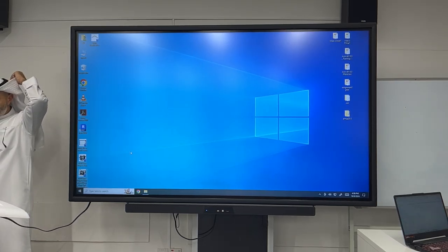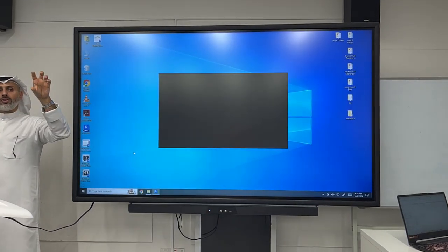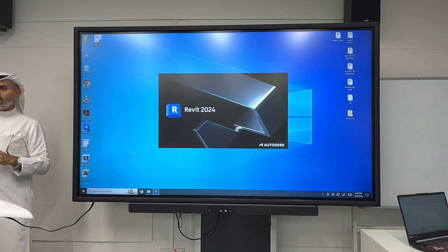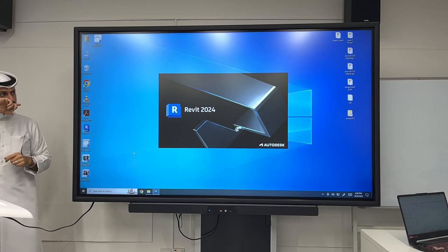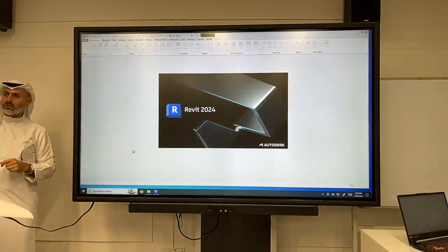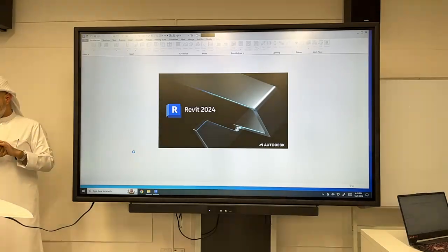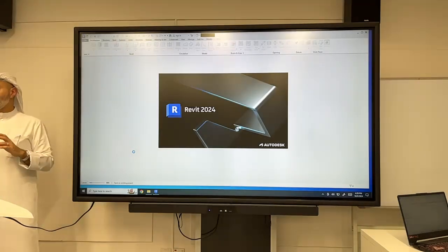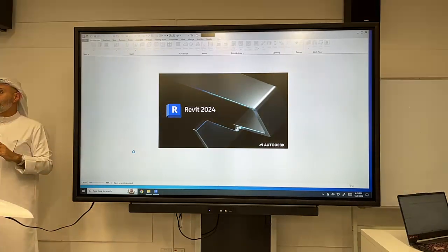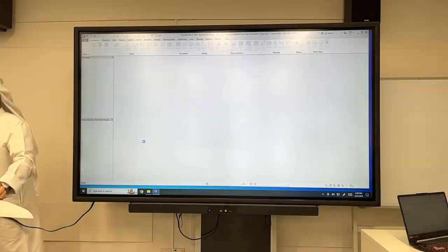Okay, I want you to open your project, but any view in your project, so floor plan, elevation, anything. Go to Manage, and then next to project units or project information, that will transfer project parameters. Oh, sorry, transfer project data. Not parameters, what is it? Transfer project standards. It's under Manage.